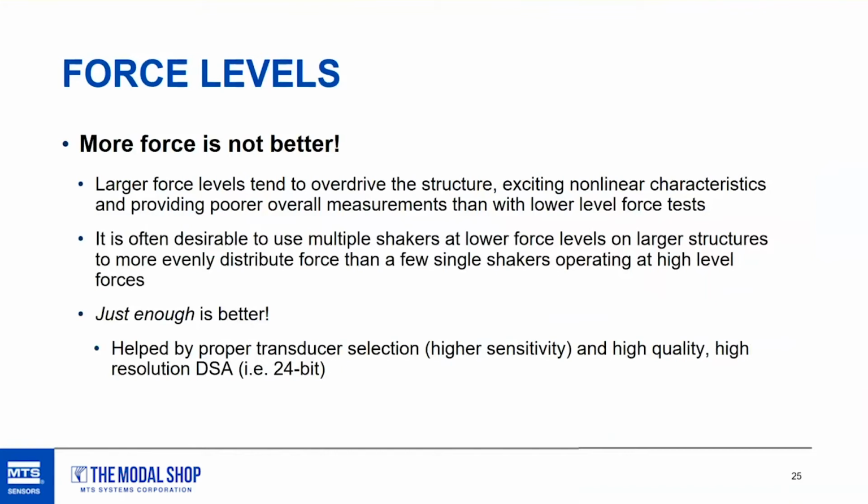So if you're putting too much force into a structure, you always have the risk of overdriving it and starting to drive some nonlinear characteristics of the structure. And again, if you can use multiple shakers, you can better distribute that energy, and the force levels that are required are definitely lower. So the rule of thumb here is just enough is better.